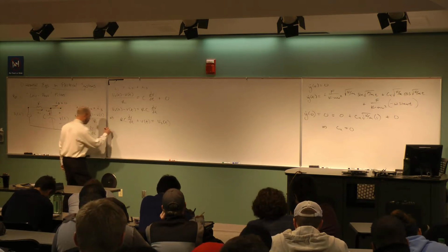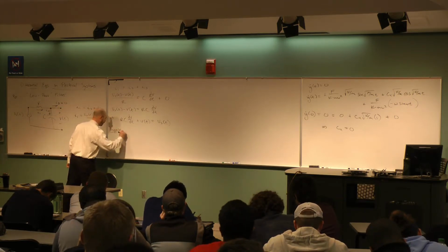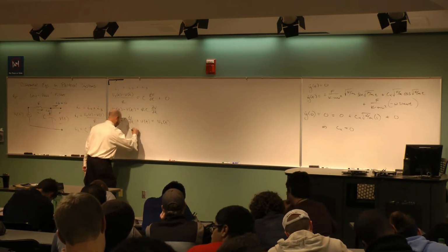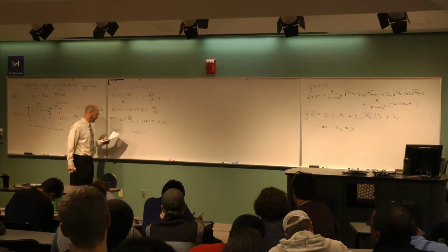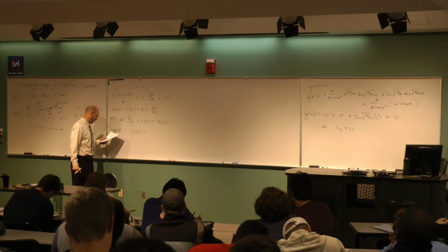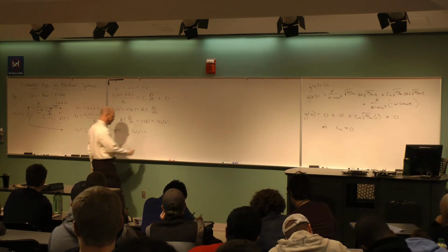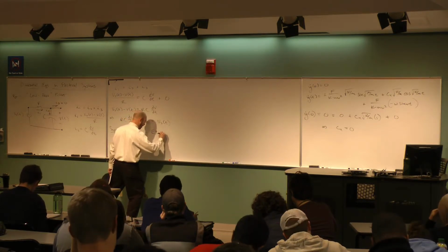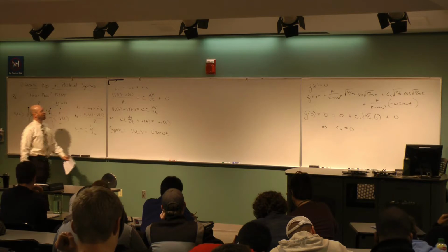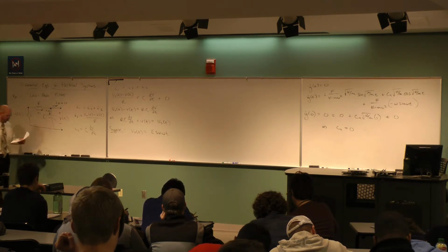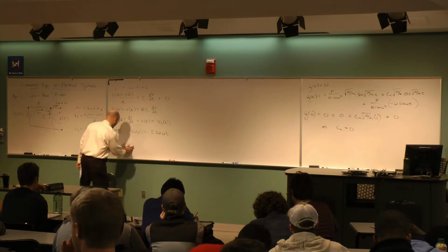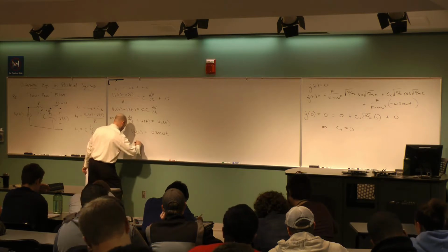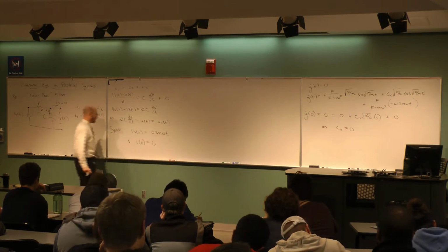So let's suppose that I apply a source that is sinusoidal. Let's suppose that source is an alternating current, alternating voltage in this case, Vs of t. What I'm going to use for this one, we used a cosine for the vibration of the spring mass, let's use a sine: E times the sine omega t. Capital E is the amplitude of the source voltage. Let's also assume, if this is a first order equation, that my initial condition is I have no voltage across the capacitor.